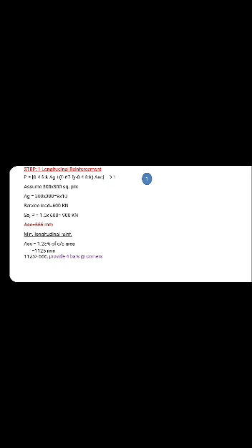Step 1. Longitudinal reinforcement. P is equal to 0.4 Fck Ag plus (0.67 Fy minus 0.4 Fck) into Asc. Assume 300 by 300 square piles. For loads in the range of 400 to 600 kN, 300 square piles will be sufficient.